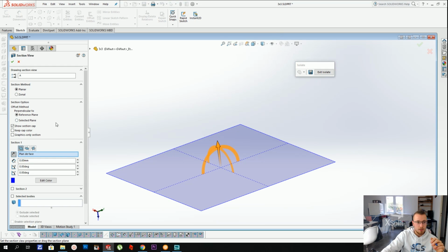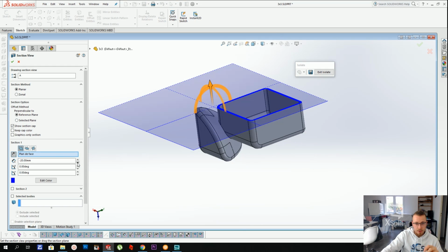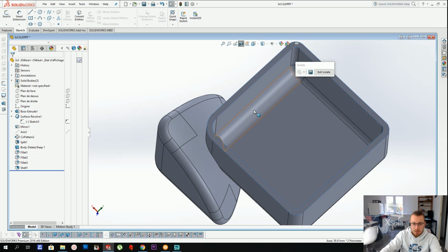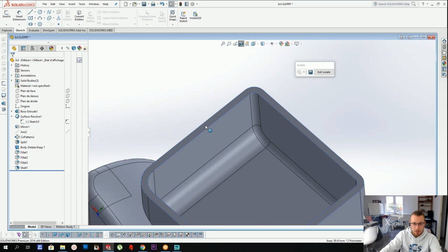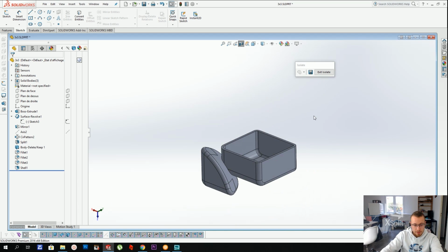So if I do like a section cut and go through the piece, you're going to see that here it's empty, and this is the only surface that your printer is gonna need to fuse. So it's actually much faster for the 3D printer. And that's what makes 3D printing prices cheap. It's because the more time it takes to produce a part, the more expensive it is. And here you're using the laser's energy, etc. So the reason why 3D printing is so cheap today is because we have guidelines that we need to respect, including shelling the parts, so making them hollow. And I think that's really important that you respect that, because that's what makes the twisty puzzles relatively cheap to print.